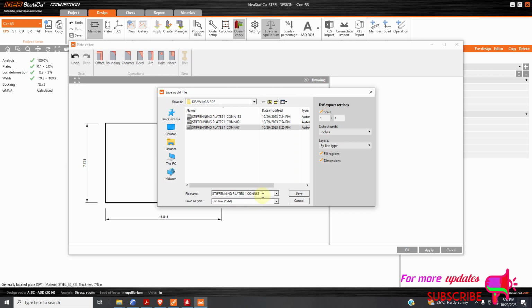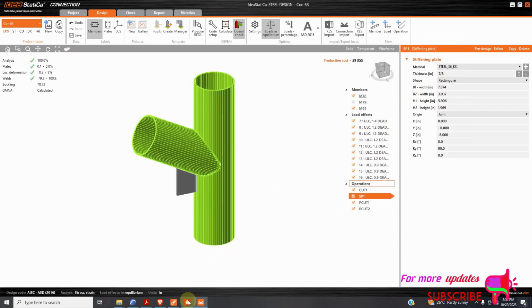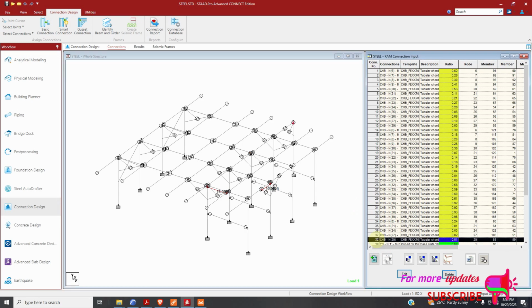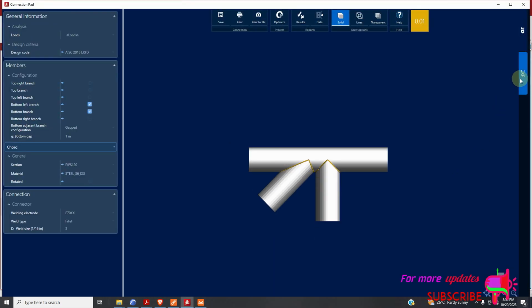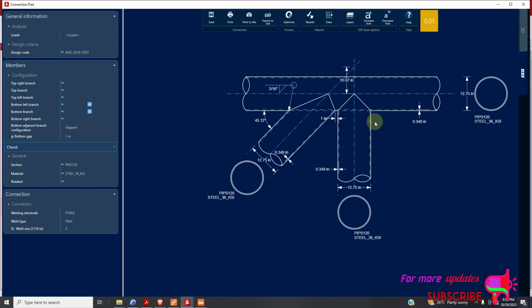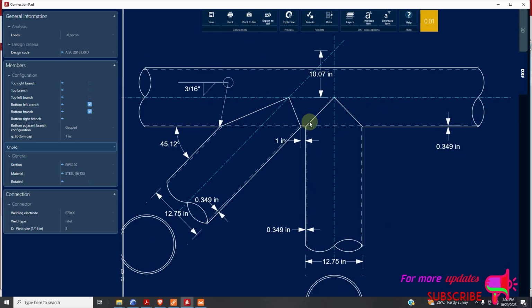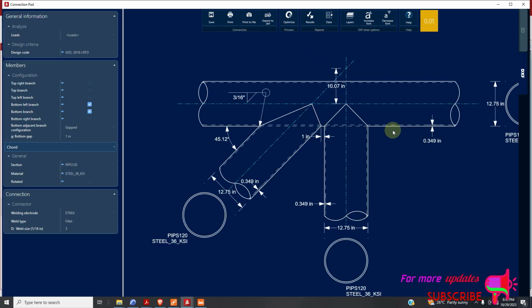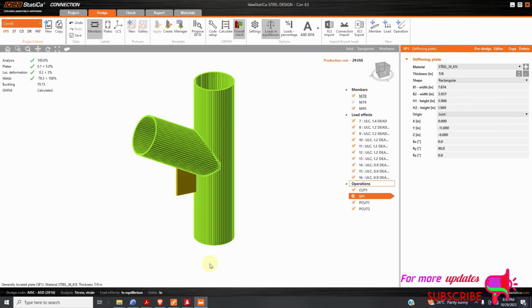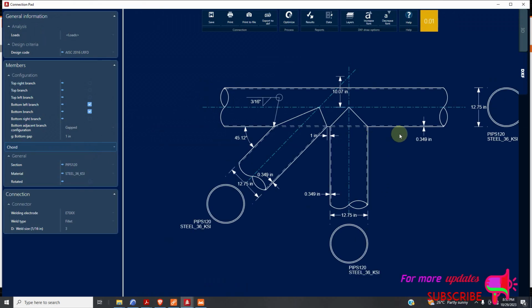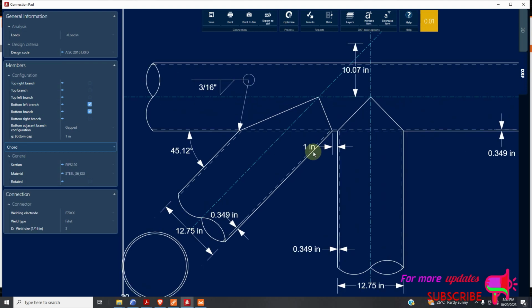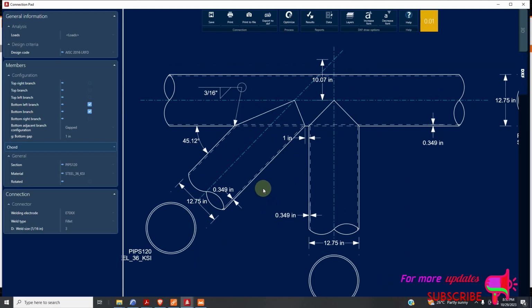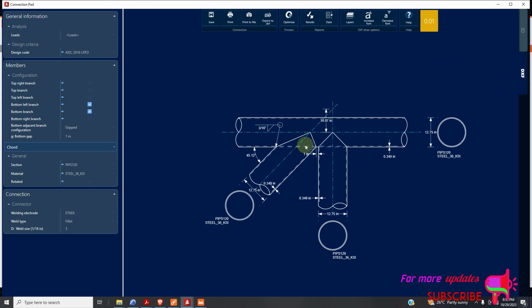So when I'm detailing these drawings, I will include all these bits in my connections, and of course using Idea Statica. Using the drawings generated here, I can easily edit and add my plates. Instead of drawing anything, I can just use these drawings from here, which I can easily export to DXF, and then combine with these plates here, then it will be easier. Just indicate that there are stiffening plates here in either ArchiCAD or AutoCAD. I advise people to use ArchiCAD and AutoCAD. So just edit this and your detailing will be complete.